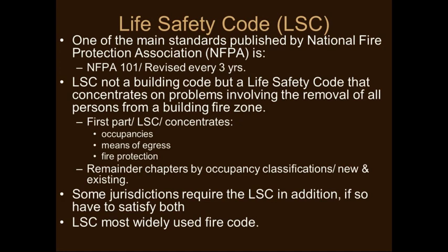Now, the life safety code is not a building code, but it's a life safety code that concentrates on problems involving the removal of all persons from a building fire zone. So they concentrate mainly on occupancy, means of egress, and fire protection. You'll just have to have an understanding, and we'll be bringing all this out throughout our semester. Now, some jurisdictions require the life safety code in addition, so you'll just have to research your jurisdiction.